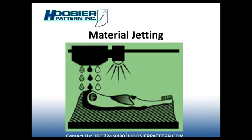They go by the trade names of PolyJet, ProJet from 3D Systems, SCP, which is smooth contour printing, MJM, multi-jet modeling, and you can get a very high degree of accuracy and full color parts. And you're also able to get multiple materials in a single part. This is huge. The main thing that foundries use this process for is for consumable patterns for the investment foundry.